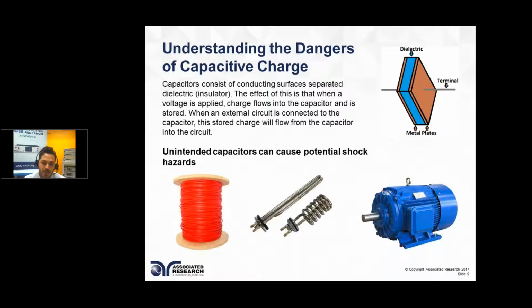So how does a capacitor work? If I go to 1,000 volts, I've just charged my cap to 1,000 volts. But if you use the ramp down feature that comes with our high-pot testers, that ramp down feature is theoretically stepping it down to 800 volts, 600 volts, 5, 4, 3, 2, 1, to the point where you've completely discharged that DUT.